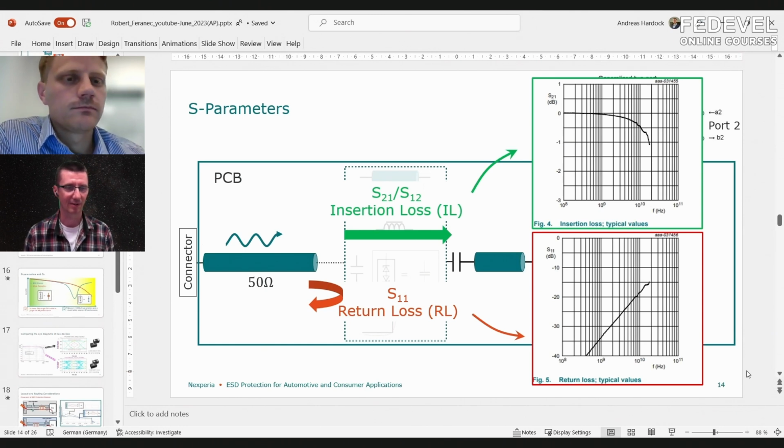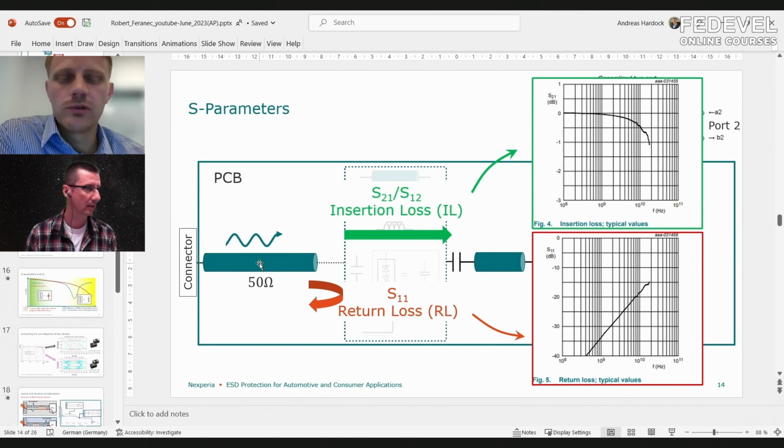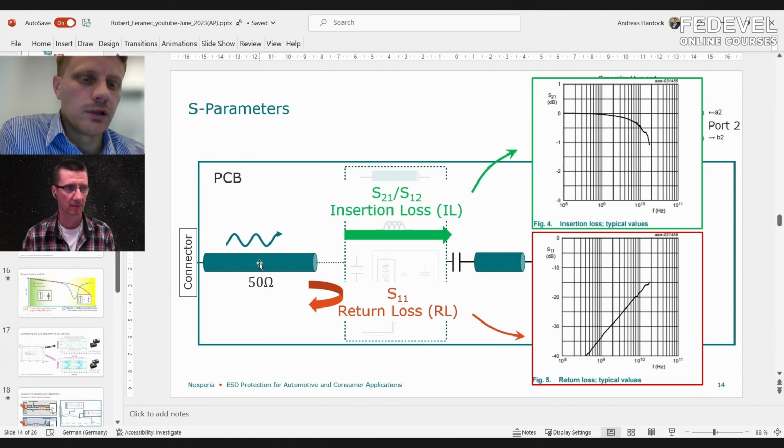Maybe it was not a very clear question, but I hope people will understand or they will ask. That's a good point. You can get a really good idea using the scattering parameters how much of your signal you will lose or you will transmit. This is exactly the idea behind having scattering parameters. And they are related to your system impedance, which is very important in high-speed signaling, whether 50 ohm or 100 ohm, so single-ended or differential.